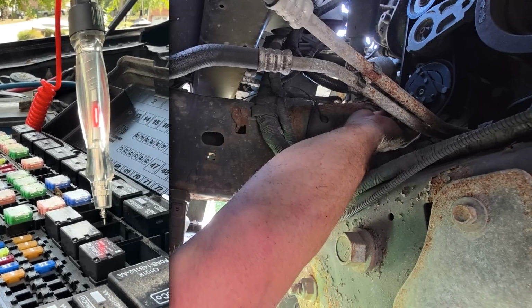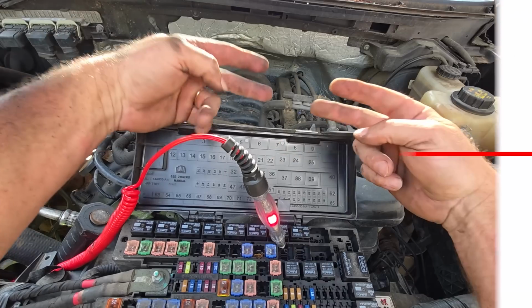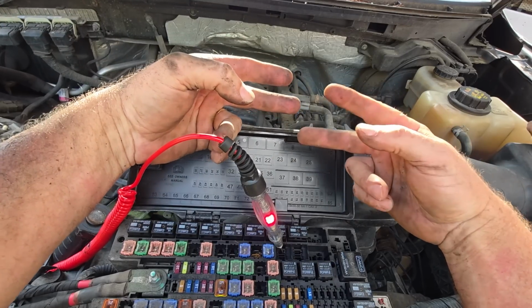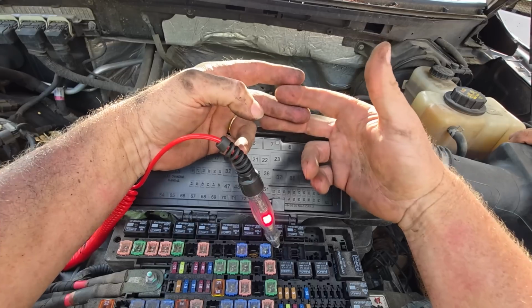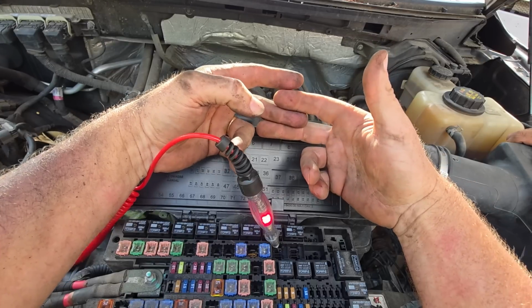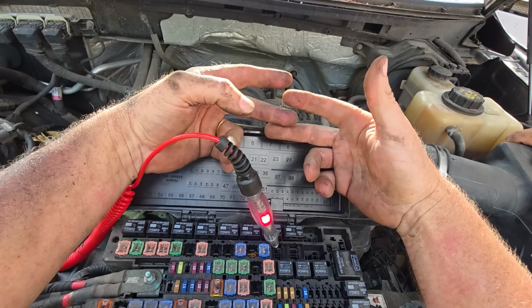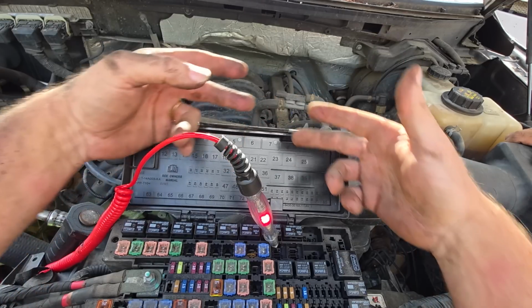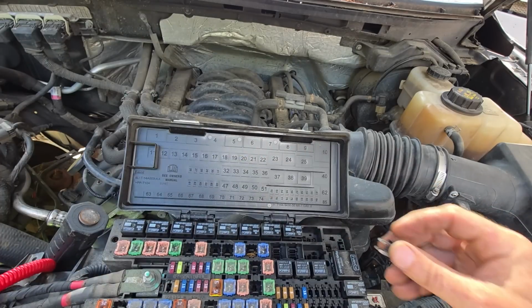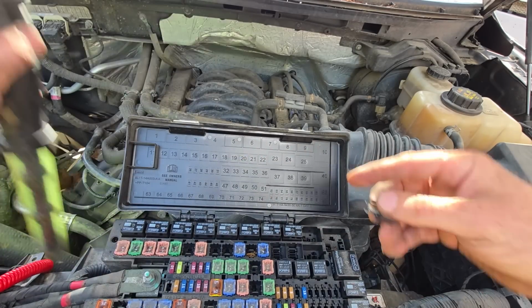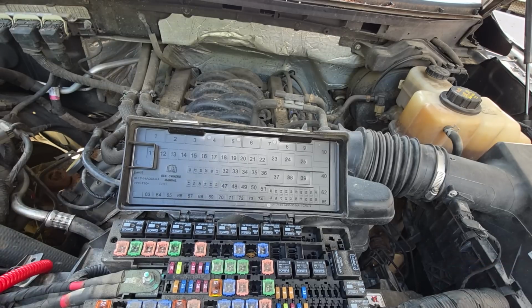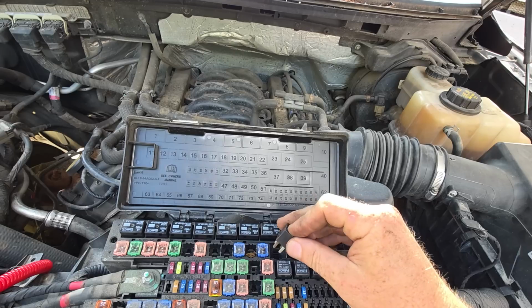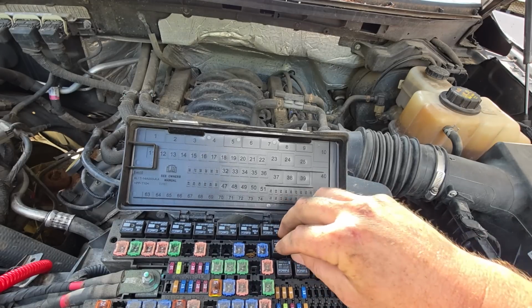Nice. Okay. So ultimately what you have is 2 male and female terminals right in that connector. With that harness being loose, that's just sitting in there wiggling all the time, which opened up the female terminal. So all I did was snug the female terminals up and plug it back in. Ultimately what needs to be done is that harness needs to be re-secured so this doesn't happen again down the road. I can't reach where that plugs. I hope I trade the truck in before then. Okay, good. I'm good with that. Either way, we know where our problem's at.